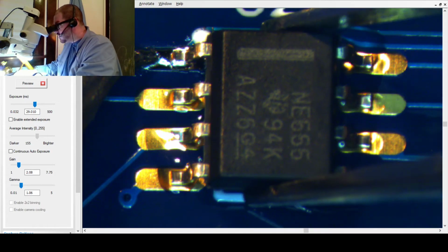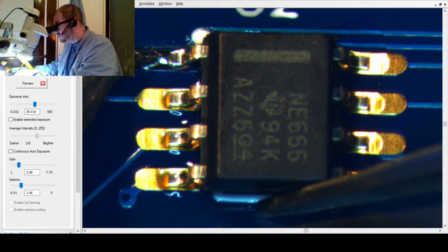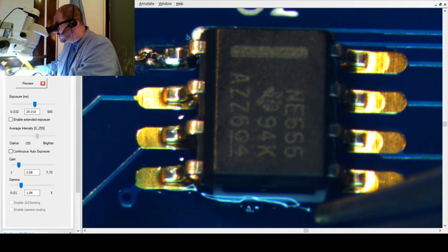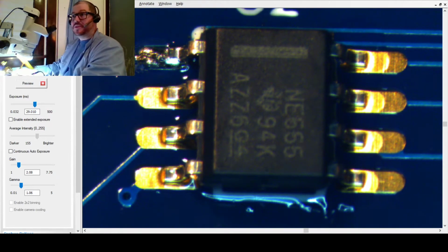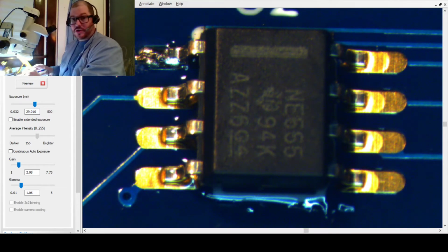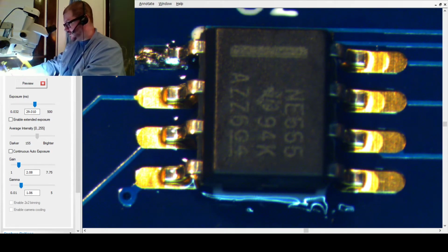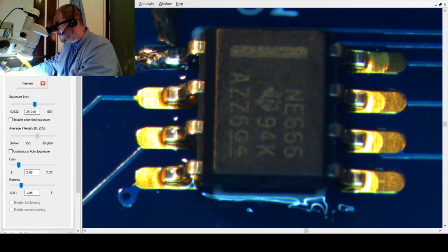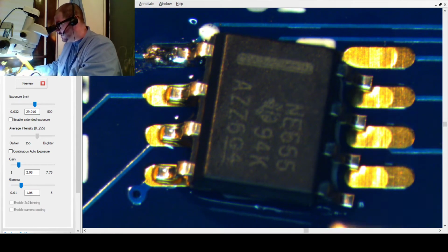I want to watch that solder essentially creep up the side of the chip just a little bit, just enough to where I see it going into place. I don't want to stay there for too long, but I've got it basically aligned at this point, which is kind of nice. I am later going to touch the chip with this. In fact, if I take the tip of my soldering iron and touch just the chip, it's oops, excuse me, that wasn't attached very well, now was it?